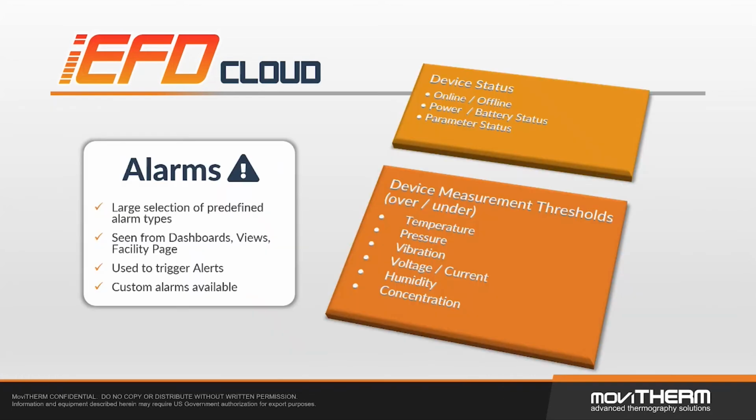What I like about the alarms is, like you mentioned earlier, Marcus, that the alarms are also not just on what is being sensed, right? So if it's the thermal camera seeing a hotspot, but the alarm is also the condition of the camera itself. Is it online? Is it working? Is it running? Or a smoke detector, or a vibration sensor, or a voltmeter, whatever. You're getting the device status or health in addition to the measurement.